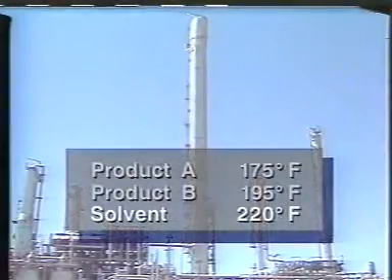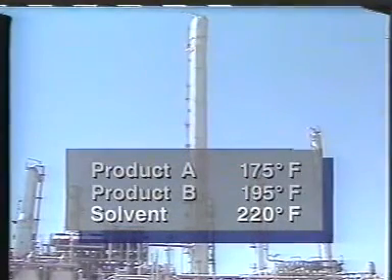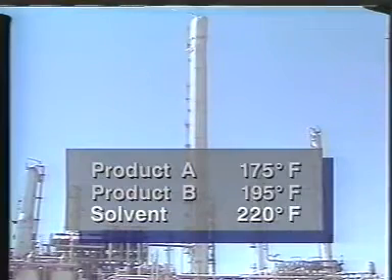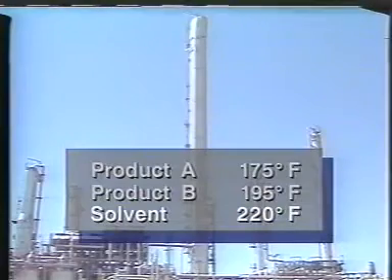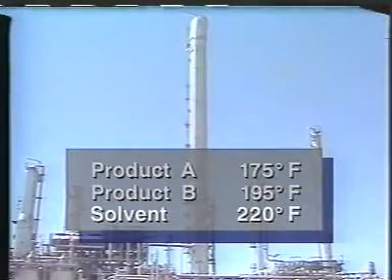The solvent used in extractive distillation has a boiling point that is considerably higher than either of the components being separated. Since it is heavier than both products, it falls to the bottom of the extractive column without being vaporized. The wide boiling point difference between the solvent and the component it absorbs allows us to separate this mixture by normal distillation.